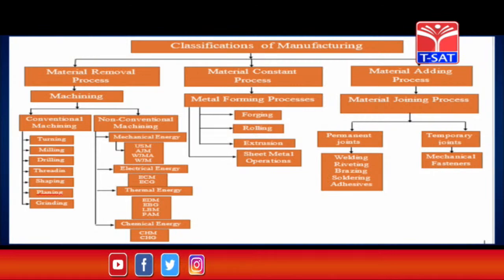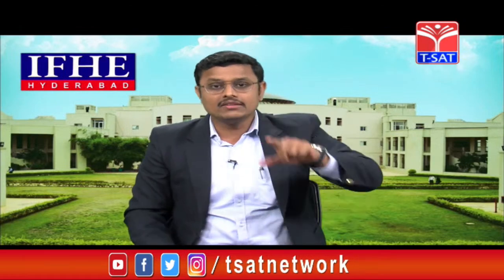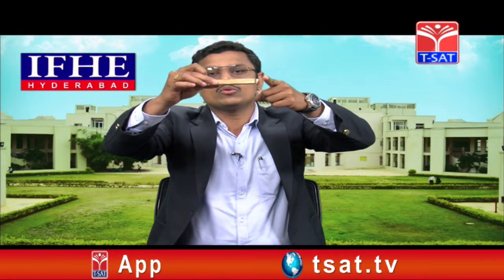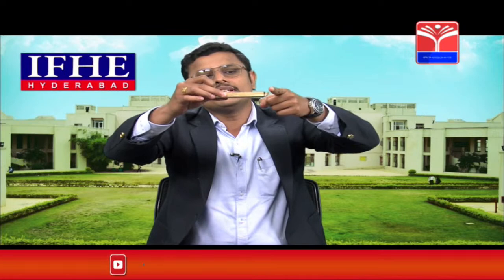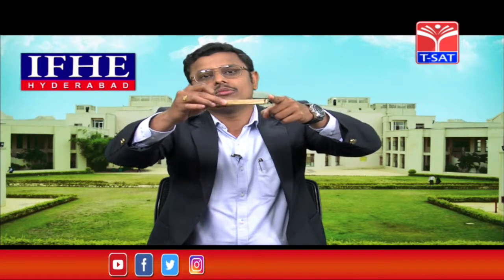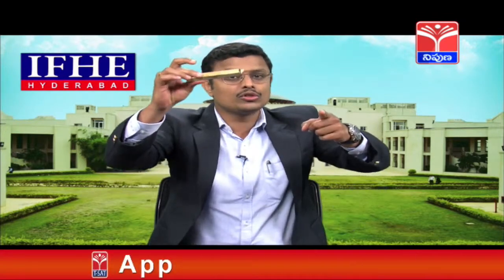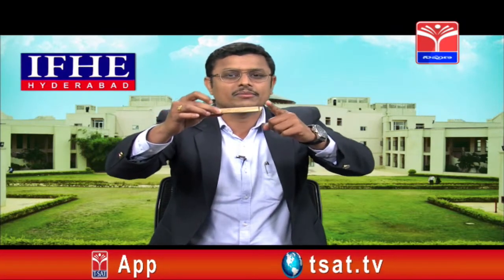Sir, what is the difference between conventional and non-conventional? Very simple, again very simple. In conventional machining, the tool is directly touched to the workpiece to remove the unwanted material. That is the first condition. And the second condition is the tool should be harder than the workpiece material. These two conditions apply in conventional machining operation.